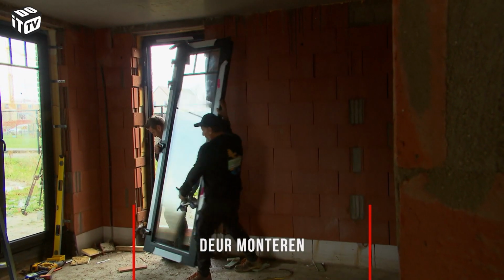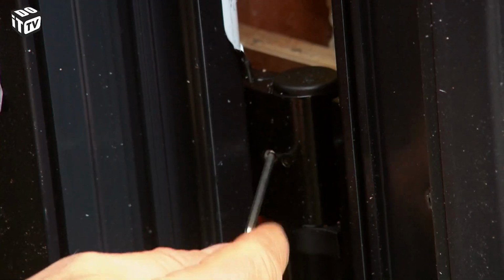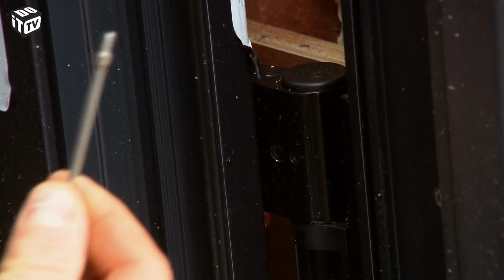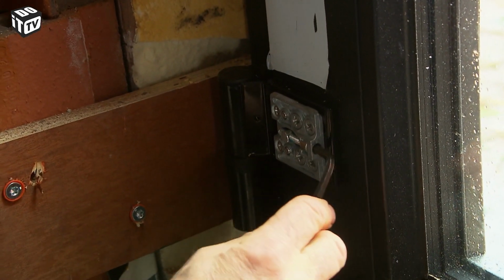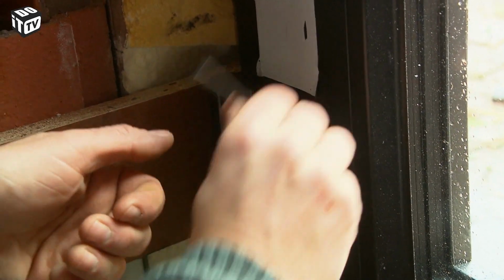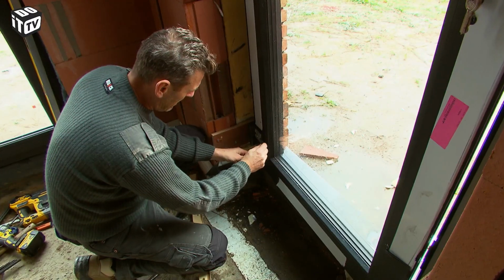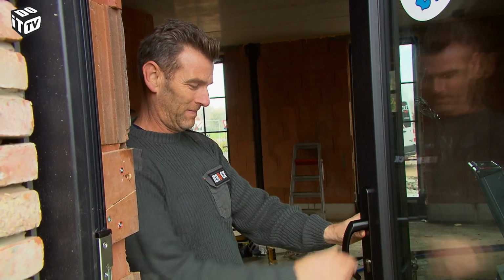Bring the door and attach it to the lower wing first, just like before with the window. Small chance everything's correct as per manual, you can still slightly adjust the hinges. Remove the set screw and cover so you can adjust the hinges until the door sits evenly everywhere and can open and close smoothly. You quickly fit the door handle.